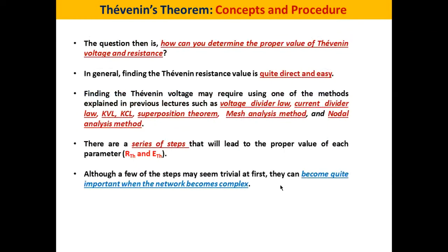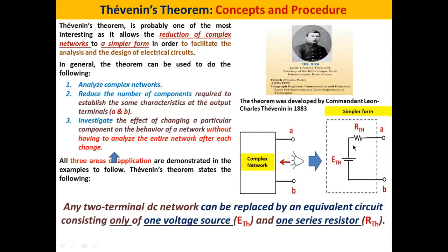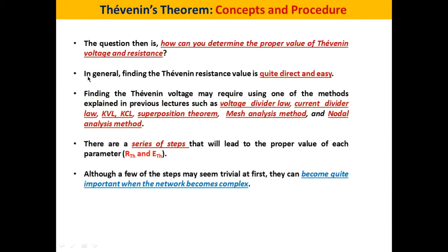So to apply this theorem, of course, we first have to ask: how can you determine the proper values of the Thevenin voltage and resistance? As you can see here, we have to determine R Thevenin and E Thevenin. In general, finding the Thevenin resistance is quite direct and easy, because we have learned in previous lectures how to determine the total resistance seen from two terminals.